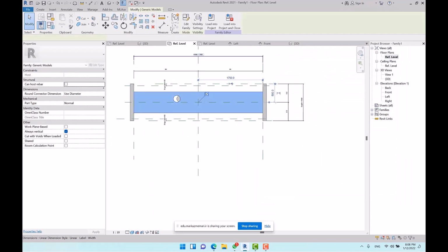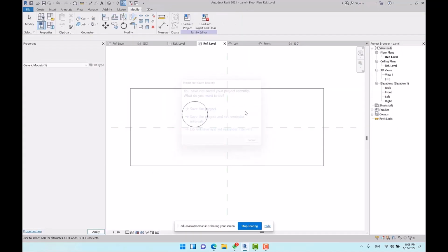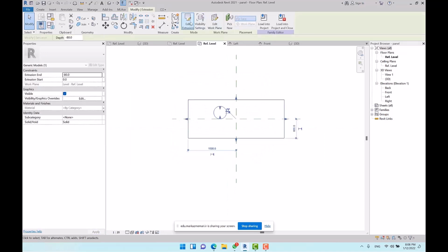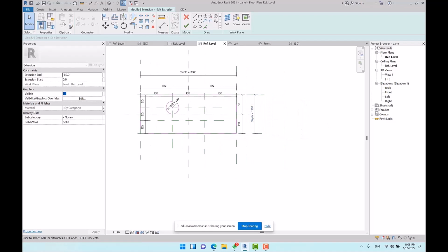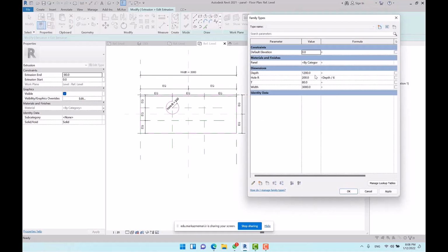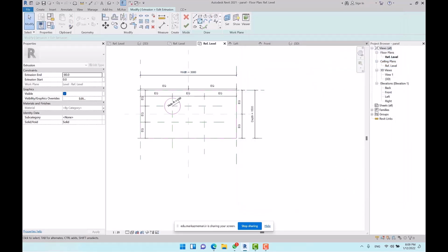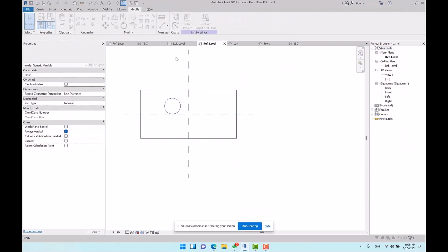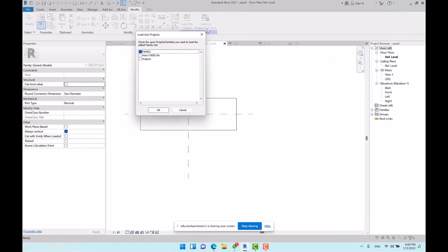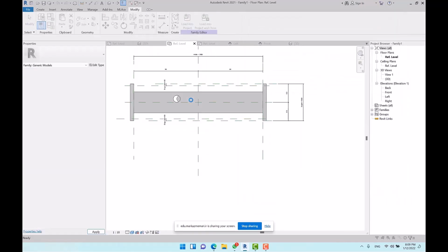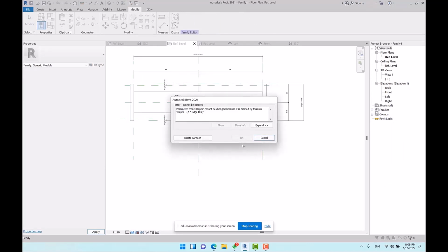I want to open the edit family of the nested family, since there is something wrong here with the panel depth. As you can see, here is depth. Let me test the parameter. 1500 for depth. Apply. This is correct. I mean, it is working accurately. Finish. I specify 1000. Apply. Very well. I load it into family 1 this way. Override.